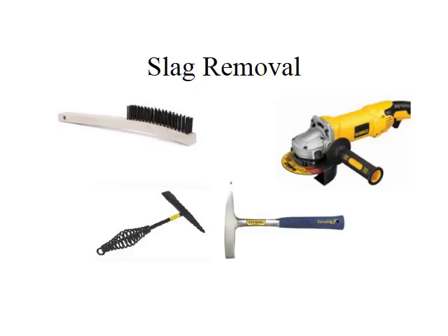Removal is usually done using manual or power tools. Manual tools may include a welding or chipping hammer, which has a pointed tip at one end to break up large chunks of slag efficiently, or wire brushes and files. Power tools can include angle grinders with grinder discs, or wire brush wheels, or even pneumatic chipping guns. Many times a file is used to clean up the toe of the weld.